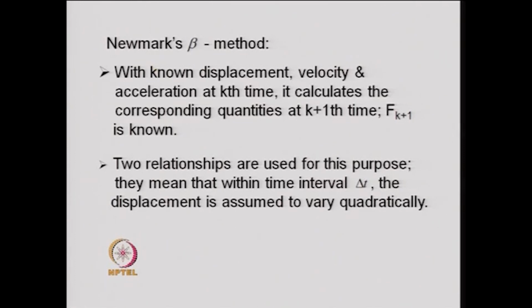The advantage of this solution is that if f tau, or the force, is not an integrable one, then in any way one has to go for a numerical integration. So, instead of doing that numerical integration, one is using the known solution for a triangular pulse, rectangular pulse and a damped free oscillation. So, using these three solutions you are able to tackle the problem.